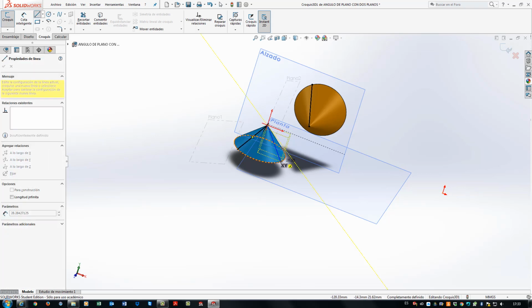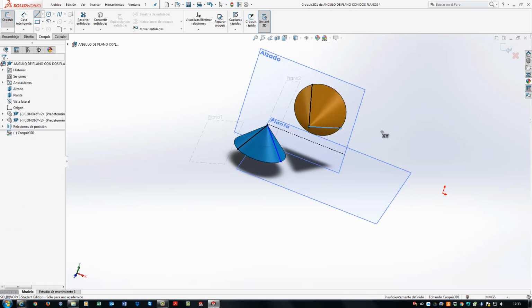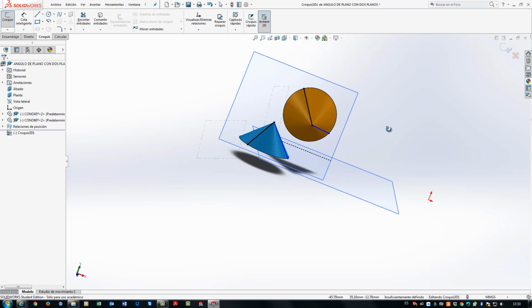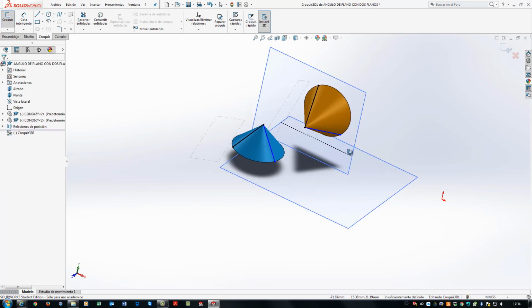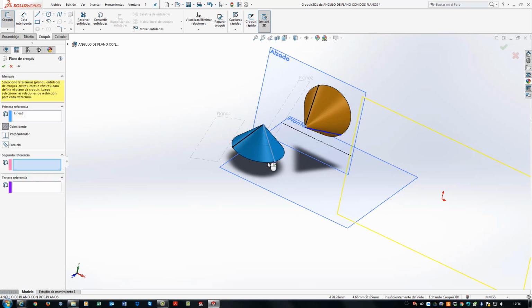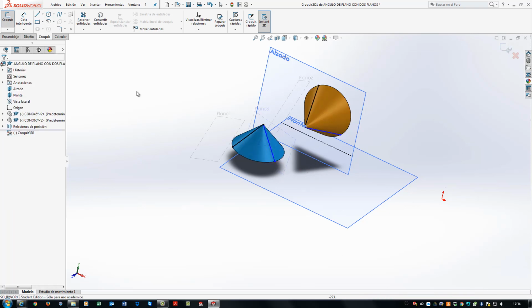If we would like to obtain another solution, another plane, which also will fulfill having 45 degrees with the horizontal plane and 60 degrees with the vertical plane, we will draw another 2 generatrices, one on each cone. We will place these lines in a slightly similar direction. We create the planes on top of these 2 generatrices, tangent to the cones.